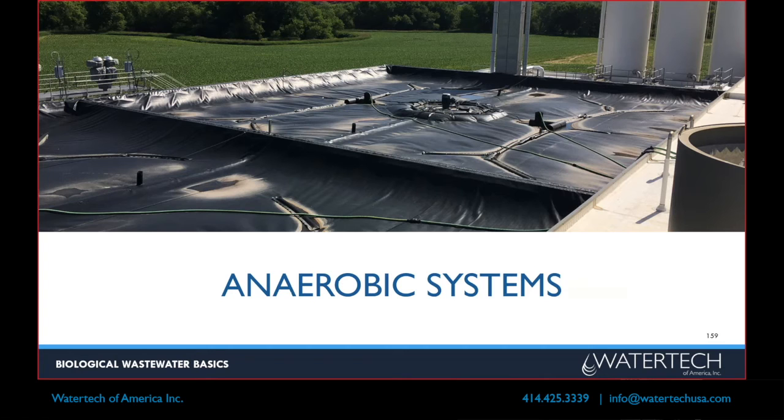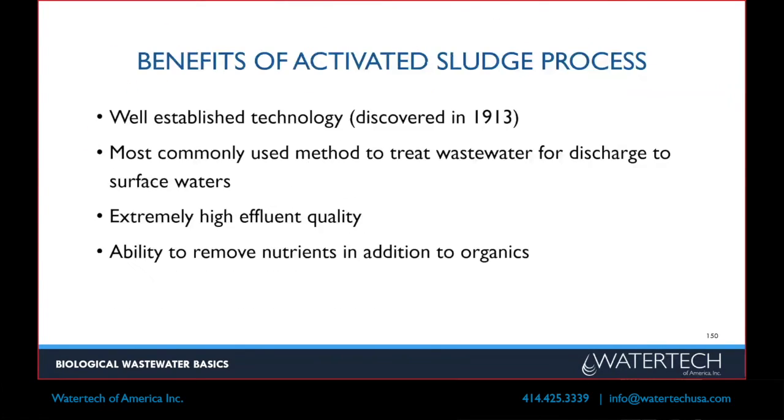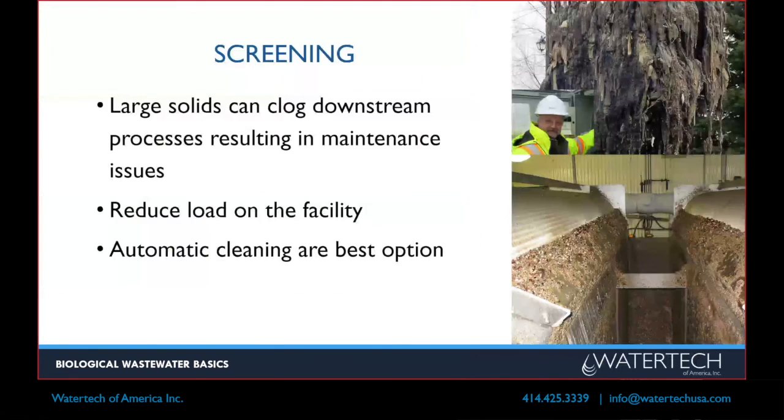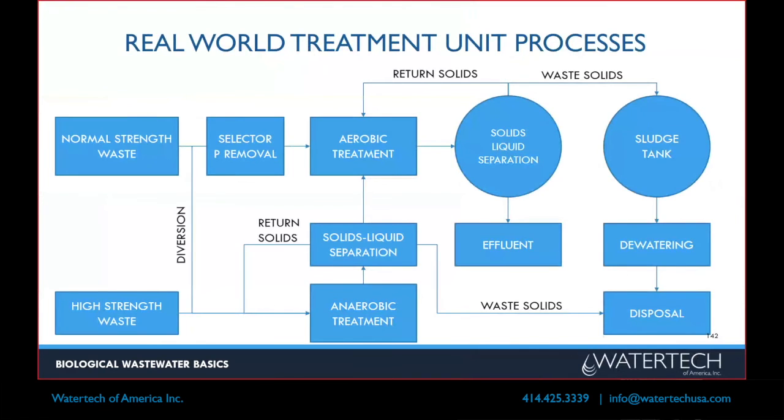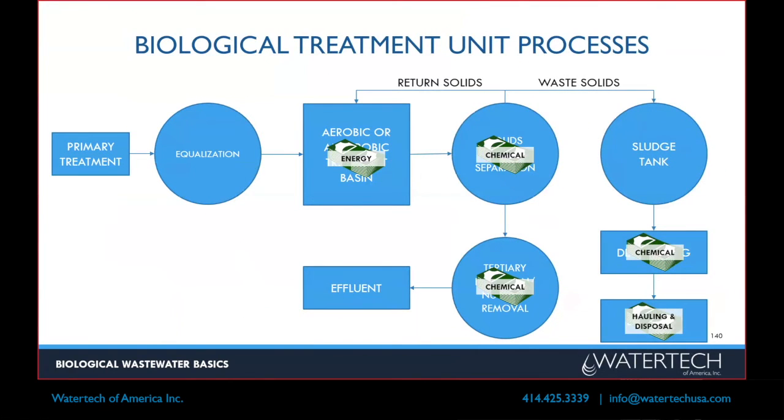Questions on aerobic? One of the things I should mention, and we should probably add it to this slide, is you hear about membranes a lot more in wastewater applications these days. I'm going to buzz back really fast just to give you some perspective. We talked about where these costs come in, and a lot of times the cost is in the solids liquid separation. If you think of this as a gravity clarifier, you have to feed a little bit of the flocculant to help settle that.